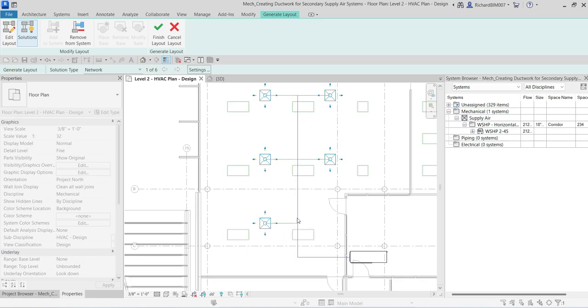So to modify it, let's go to Edit Layout. Let's click this one. And then you can see your pointer becomes a pointer with a magnifying lens. So we can click one of the pipes or one of the duct mains. Let's click that, and then you see there's a move icon. So I'm going to hold that and then drag. Maybe I'll just put it somewhere there. Okay.